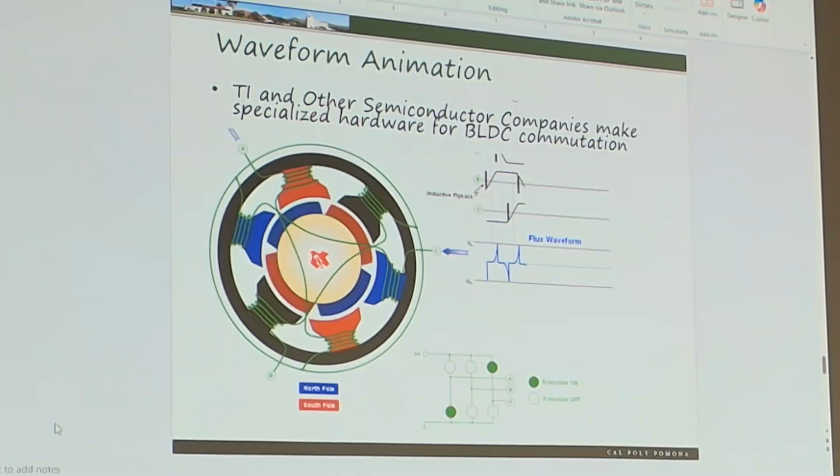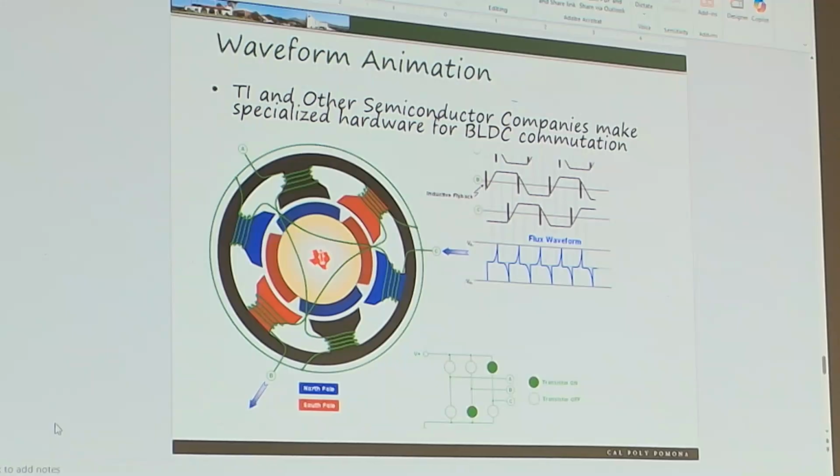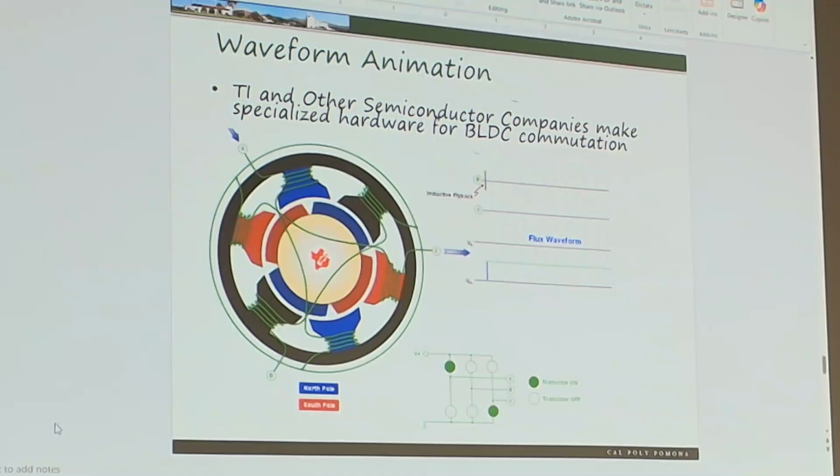So we have field-oriented control drivers, which are known as FOC BLDC drivers, or FOC for field-oriented control. That's a very good control system. So let's think about feedback systems now. I'm measuring current, and I'm adjusting the field of that winding to drag that motor exactly where we want. That's FOC BLDC control. That's the pinnacle of BLDC drivers. For Brex, we're not there yet, but we want to get there. That's a planned approach. Right now, we're just doing on-off trapezoid that you saw on that previous slide.